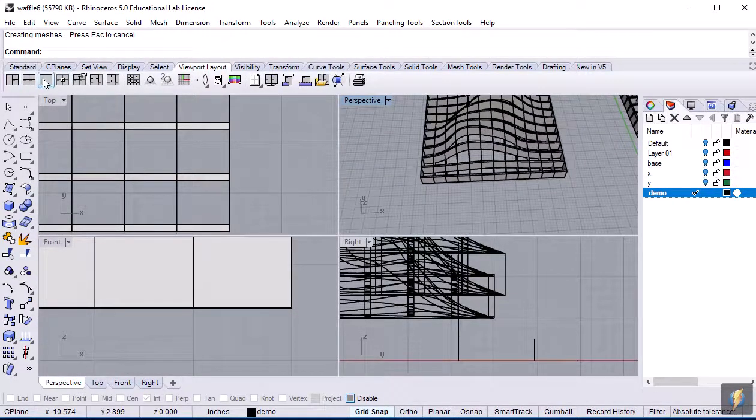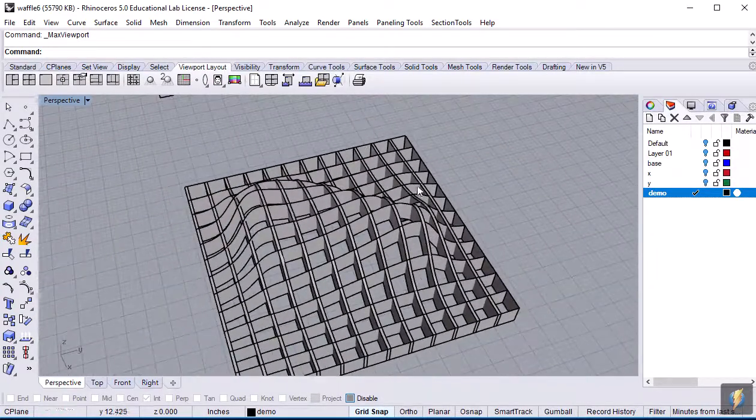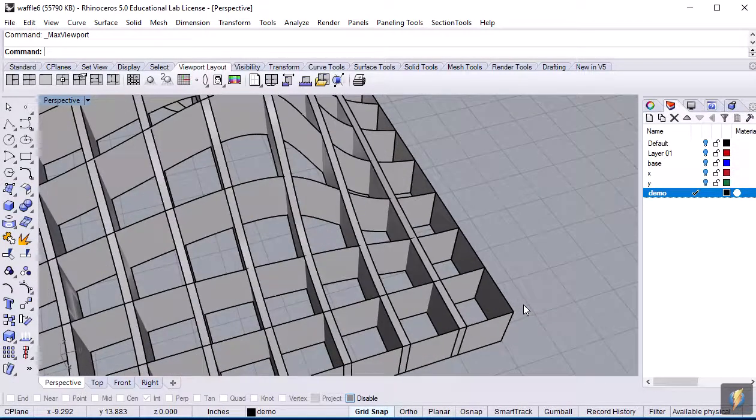So the reason why I didn't select the last one is because that last one, if it extends out 1/4 of an inch or whatever the thickness is, then I no longer have a 12-inch piece, right? It would be 12 1/4. So what I'm going to do, I won't show you this, but basically you'd go through the same step, but you'd move the direction going inward. And also, same thing with this piece, this will go inward.